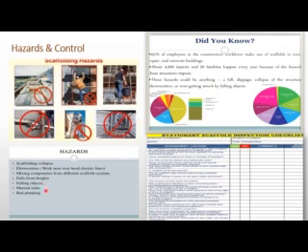To control the hazards, one needs to adhere to standard procedure and use standard scaffold material, follow OSHA's code 1926.451 to 454, give regular briefing and training, ensure proper supervision and inspection by an authorized person, ensure proper fall protection and access, proper housekeeping and cleanliness, and ensure use of JSA, checklist, signage and tagging.